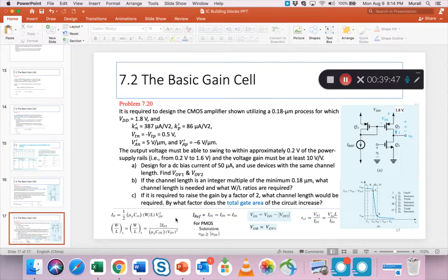For 2 and 3 it's the same, right? Because they are a matched PNP set. I reference is ID2, ID3, ID1. So for a CMOS case, this I reference is all the same drain currents.